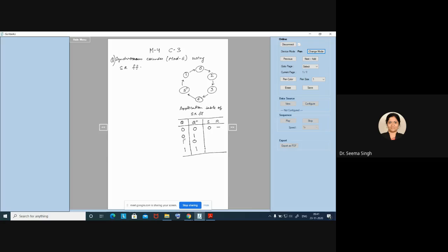Now coming to the next row, 0 to 1. 0 to 1 means my next state has become 1. So it can be the setting of the flip-flop, right? If I want output as 1, it is like setting of the flip-flop, and the setting input says 1 and 0. Do you think any other possibility is there if I want to make the output 1? There are no other possibilities. It is only setting of the flip-flop which can make the output 1 from 0. There is no toggle in SR flip-flop, so it can't happen.